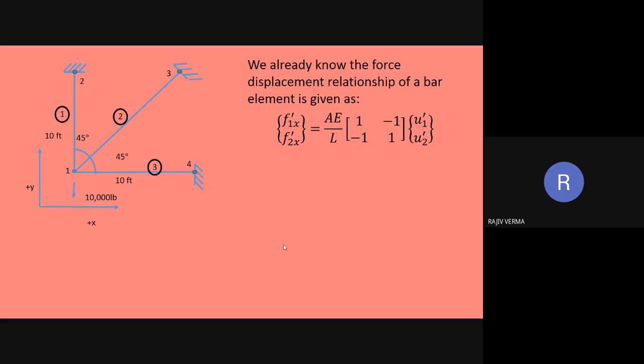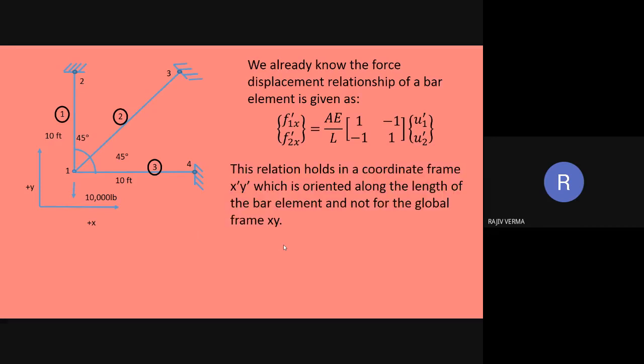Also note that this relationship is applicable only in a particular coordinate frame in which the x-axis is oriented along the length of the bar element itself, and is not going to be applicable for any other coordinate frame.